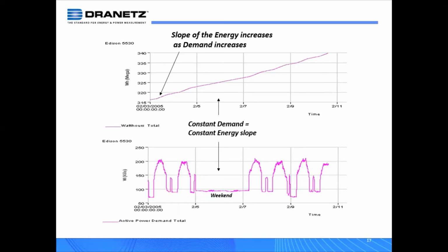An example is the kWh meter on your home, whether it be one of the new static meters or the old electromechanical meter. If you were to go out at, let's say, noon and read the value for kWh, and then you go back out at 5 p.m. and read it, you're going to have a new value. So basically, it's an accumulation. And if you want to determine the usage for that period, you just take the delta of the two readings. That's basically how kilowatt hours is recorded.